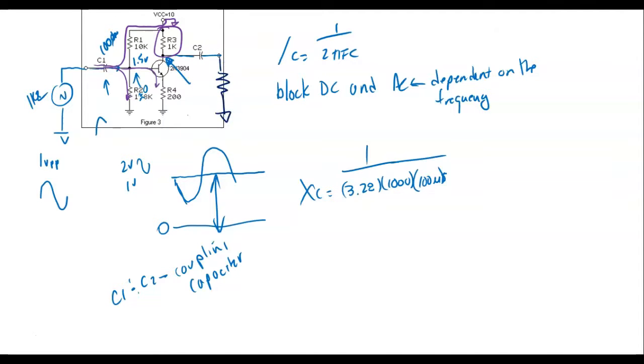So if I load the amplifier, would you expect the output to go up, or would you expect the output to go down? You'd expect it to go down. That's good. It's just like your car battery out there. If your engine's not running, go out there and put a voltmeter across your car battery and turn on your lights and everything. What do you think the voltage is going to do? It's going down, because it's not a regulated power supply.